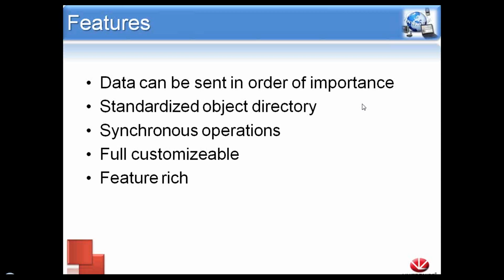It's fully customizable. We can set up how frequently data is sent or received. We can configure the communication parameters while the device is running instead of through a dip switch like we normally would have to. It's actually a ton of little hidden features that are available to you. Most of them are optional. They're not required. So I will show you how to hook up a CANOpen device as quickly as possible, just getting the reading that we're looking for, as well as show you some of the cool things we can also do with it.